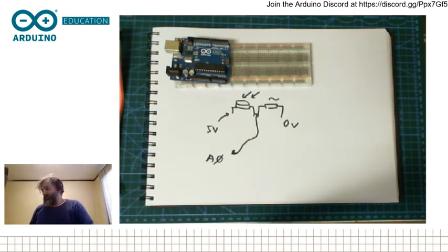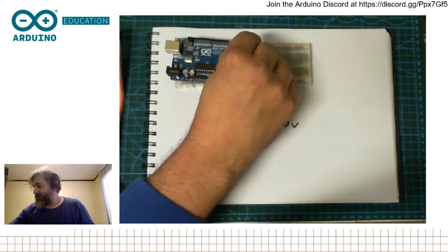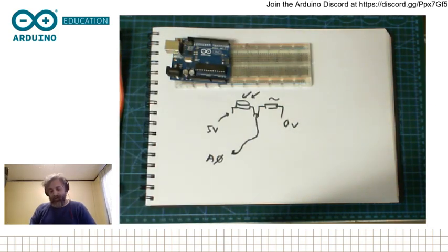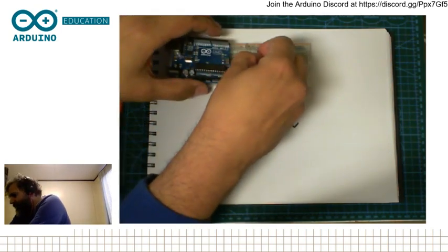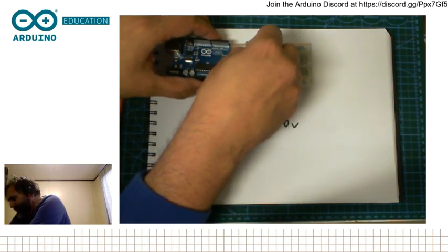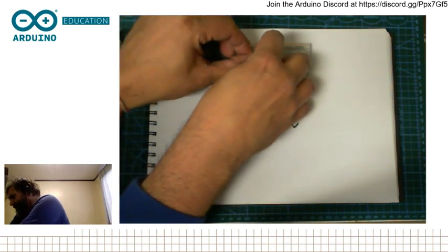So the way this is mounted is very simple. I will make it exactly as I did on the drawing. First the LDR. I'm going to choose my 1 kilo ohm resistor first, and I will mount it here. We don't have really great light in this room just yet. We just moved in, so we need to work a bit with improving the light qualities.